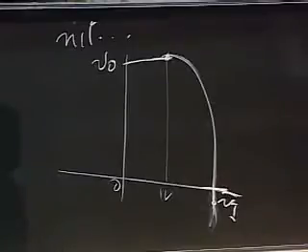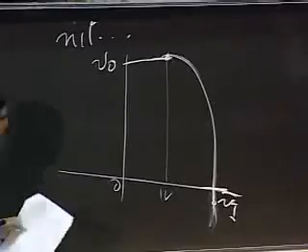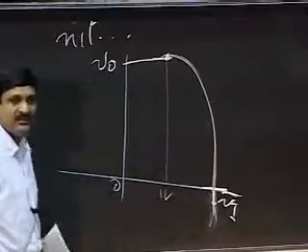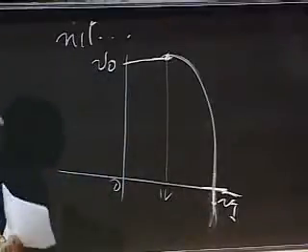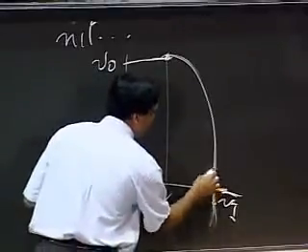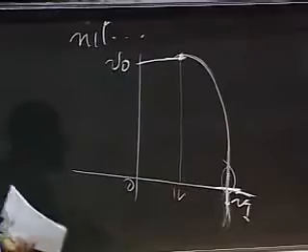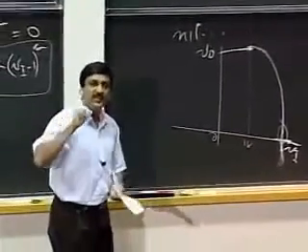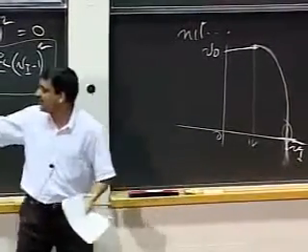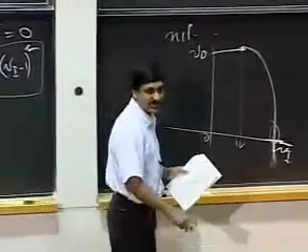So mathematically, this curve says that the device has begun to supply power. It turns out in our practical device, it's a passive device, so it cannot go here. So somewhere along here, the model breaks down. The equation I've shown you for the current source, here we go, this model breaks down. When V0 becomes very small, the model breaks down and it no longer behaves like a current source.